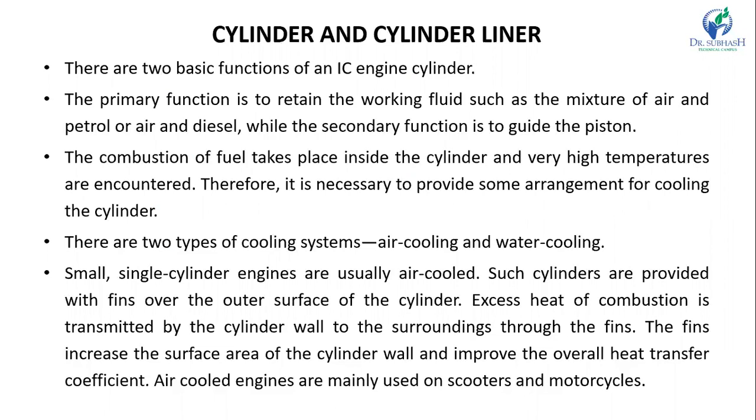Since the cylinder has to withstand the high temperature due to the combustion of fuel, some arrangement must be provided to cool the cylinder. Single cylinder engines such as scooters and motorcycles are generally air cooled and are provided with fins around the cylinder.